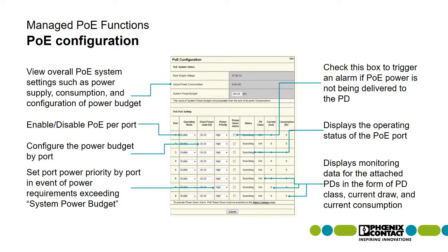Additionally, you've got the capability to trigger alarms if PoE power is halted to the device, as well as a number of basic diagnostic capabilities. It displays the operating status of the port, as well as the monitoring data for the devices. And when we get to the demo, we'll see some live data on that.